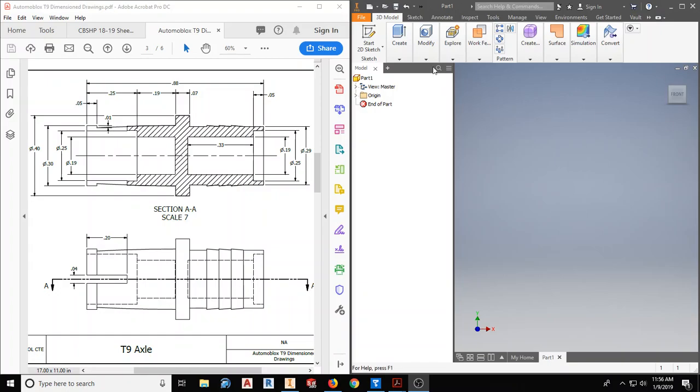All right, this video is the revolve for the axle. We're going to make a simplified version of this axle. And really, this is a section view, so it's as if this thing's been cut in half. And in the end, we're going to add this little cut for the axle here too. But we're only going to draw half of this because it's a revolve.